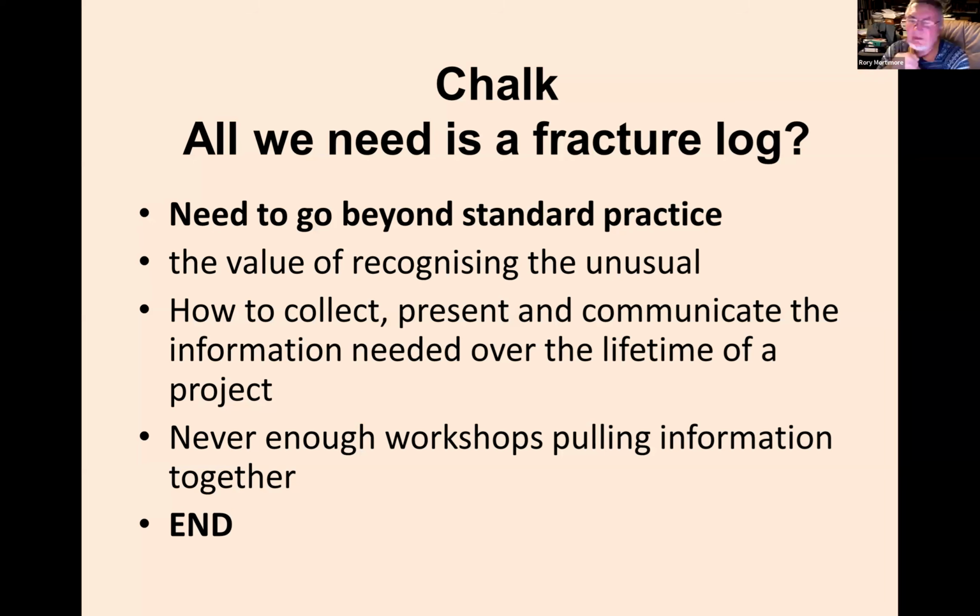Normally one thinks of the main stress field operating in the chalk, as in any rock, as being a vertical stress down through the rock mass. But if you've got things like clay seams and marl seams, and many of them, what you're doing is switching those stresses down onto the horizontal planes, and so you're actually changing the orientation of your stress axes.